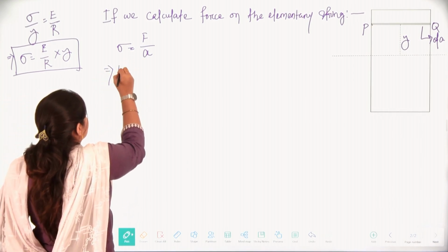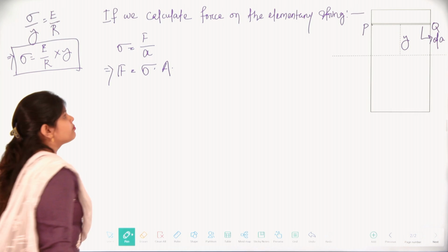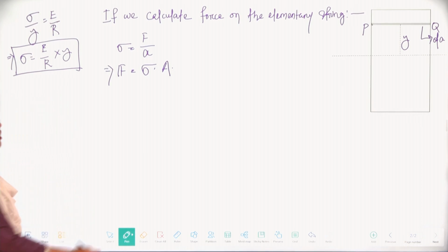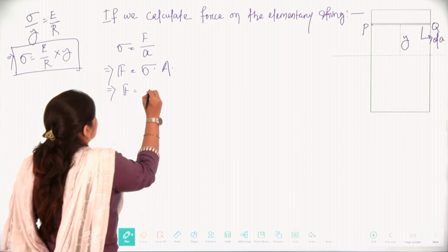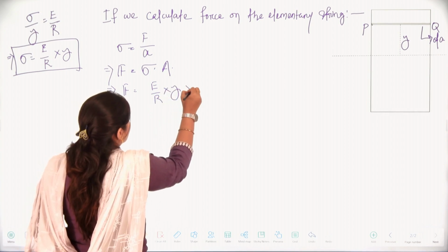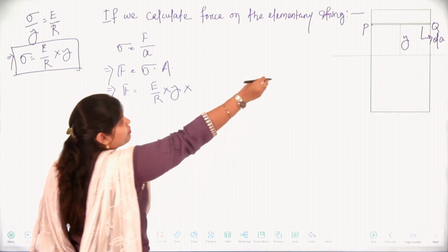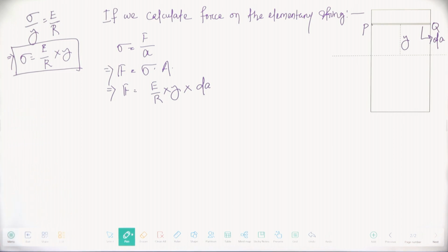So we can write force equals stress into area. Here we can write F equals E by R into y into dA, where the area is dA.